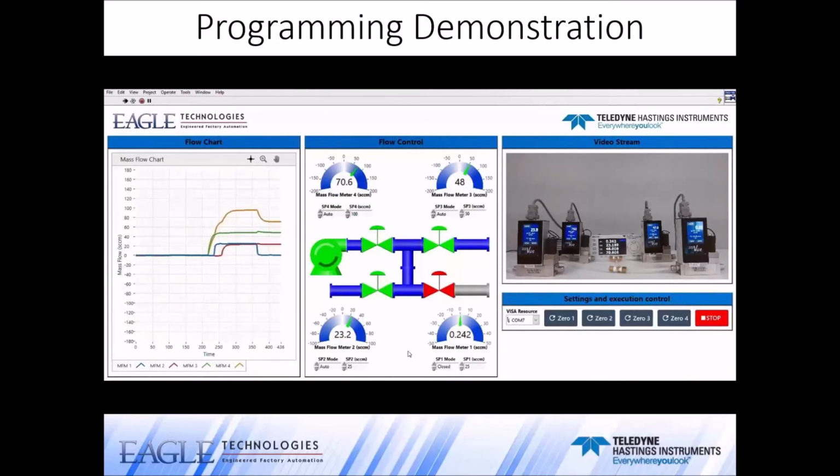We can also zero each of the sensors programmatically. For example, let's close flow meter 4 and execute the zero command on the other 3 sensors. After a brief delay, we will see that the numbers shown are closer to 0 in the front panel indicators and the THCD401 screen.